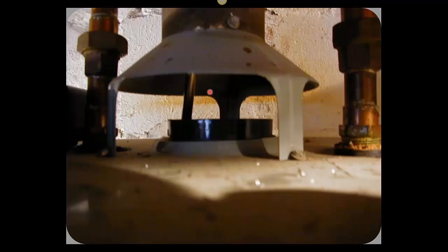So here's a real good close-up. Again, here's a water heater draft hood. You can see my probe right here. The probe is going down into the fire tube or the turbulator area. If you take your reading anywhere above this line right here, you're going to have excess air, because again, the draft hood's job is to allow air from the room to enter into the flue. So all this air from the room is going up into that flue. Okay? And that'll give you a skewed reading.